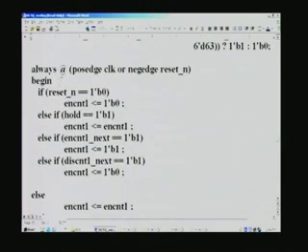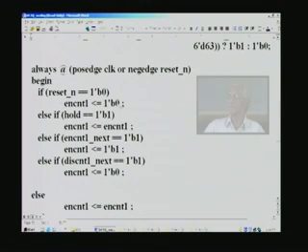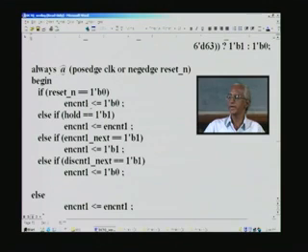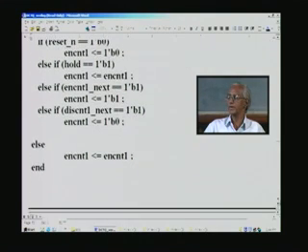So, here we have a set of always blocks, and they are all identical. First we initialize each of these enable counter 1 through counter 5, and if it is hold we just do not disturb the contents, and we enable this only when a particular condition is met. This condition we have already seen before, and only then we enable the counter. Otherwise, if a disable condition that we have also seen before is met, then we will disable this. Putting a 0 into this is equivalent to disabling. So, exactly the same thing you will see, and otherwise do not disturb, for all the other counter enables here.